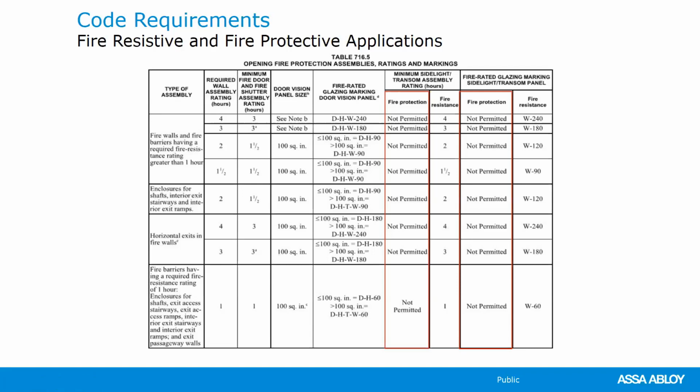In other words, an assembly tested to UL 9, NFPA 257, or as I mentioned, commonly used hollow metal. The other, if you look over here next to that fire protection, it indicates what the fire resistive should be. And if you'll note, the hourly rating on these are exactly the same as the wall rating. So, again, looking at the fact that the fire resistive assembly with glass has the same hourly rating as a wall, you want to think of this product as a wall.